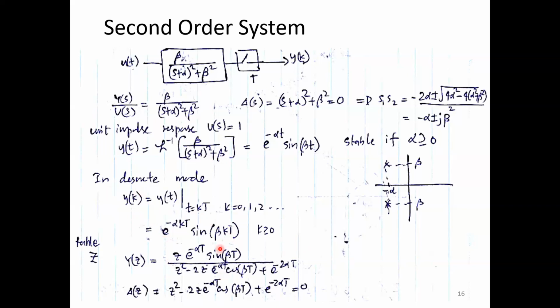Now, this is your discrete time signal. If you want, you can put some alpha and beta, and also the sampling interval to whatever value, 10 milliseconds, say 100 milliseconds, half a second, anything. And then get your k from 0 to whatever value, and then you can plot it for a particular system sampled at that particular sampling interval. So we'll see different waveforms of the same plant, okay? So sampling is extremely important because it's going to be a hardwired part of the discrete time plant. Even though you have the same continuous time plant, you generate many discrete time plants because of the sampling interval.